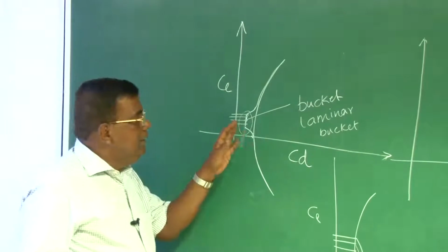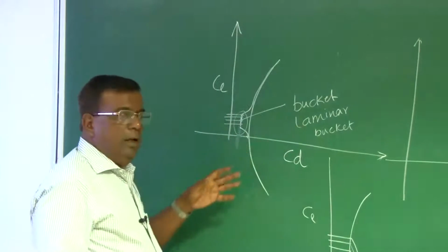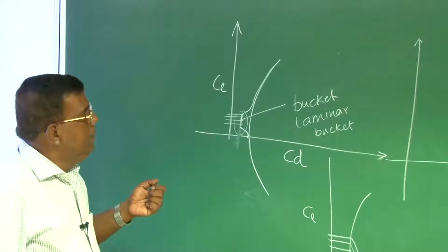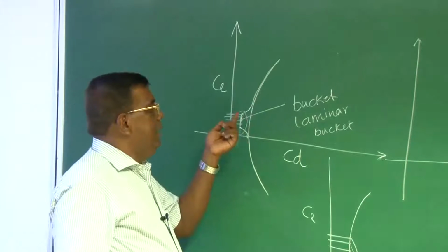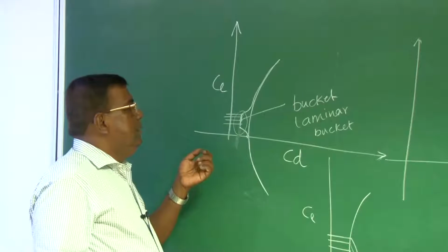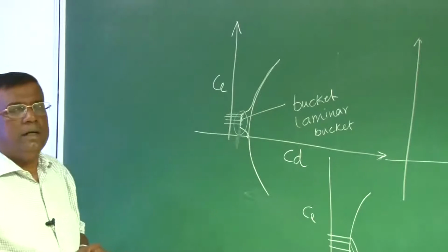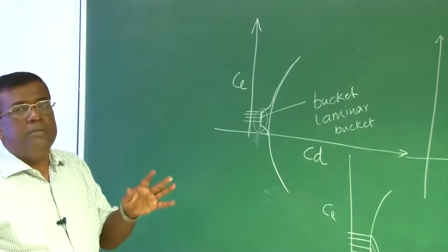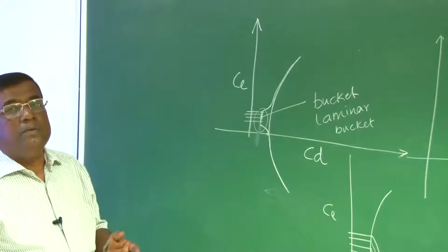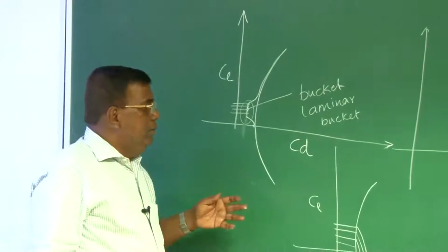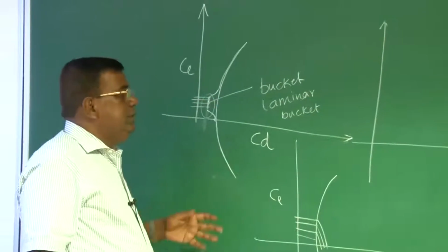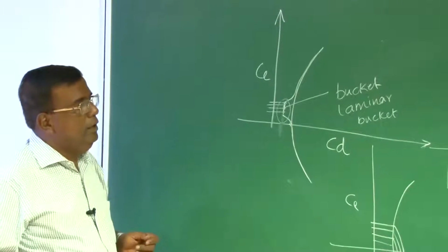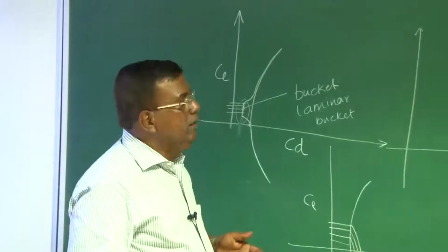But please understand, this is typically a laminar aerofoil, and nomenclature wise you will find there are 6 series aerofoils mostly. But there is an issue with laminar bucket type of aerofoil: if there is a slight imperfection in the construction, even if you find some insect material, dead material is there, the flow immediately becomes turbulent, right? But there is a trend that mostly people will be using 6 series or derivatives of 6 series or customized 6 series aerofoils. So it's called 7 series, 8 series, all those things.